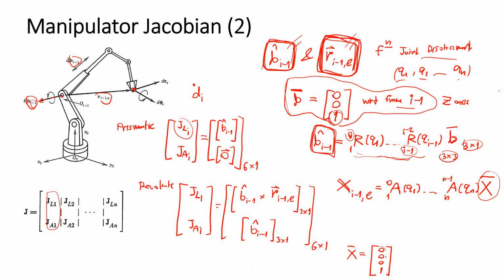The origin has 0, 0, 0 position in the frame, and it's a 4x4 matrix operation. If you remember, in the homogeneous transform, we have the 1 as one component, the last one from the 4x4 matrix. So this x bar is this one. This relates to the position of the endpoint,